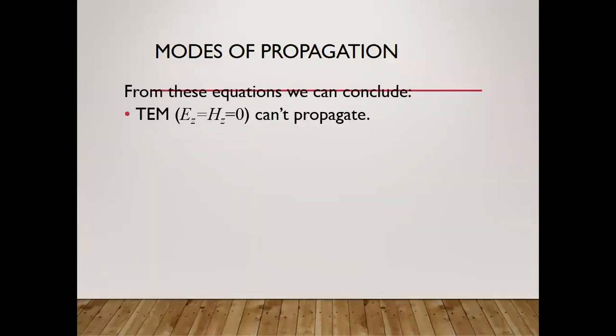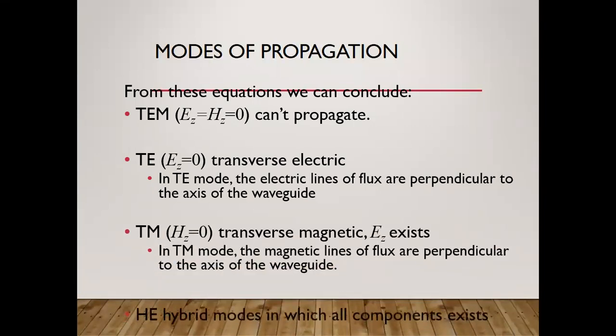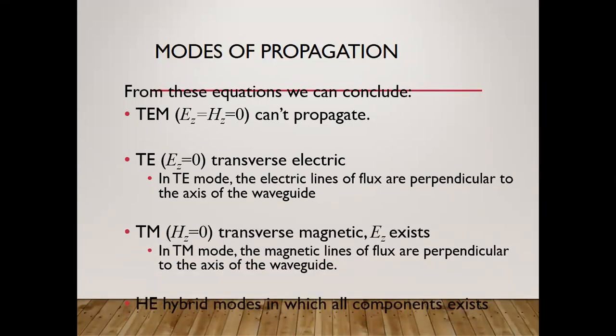Similarly, the mode of propagation. In short, we have already studied the modes of propagation. There are various modes of propagation: TE, TM, TEM. Now again pay attention to how we can write the equation. In the TEM, there is a combination of the electric as well as the magnetic field. So obviously, if you are in the Y and X plane, then my Z component will be 0, because it cannot propagate in that plane. My E and H are in the X and Y directions, then the last parameter, Z, will be treated as 0, which can propagate.